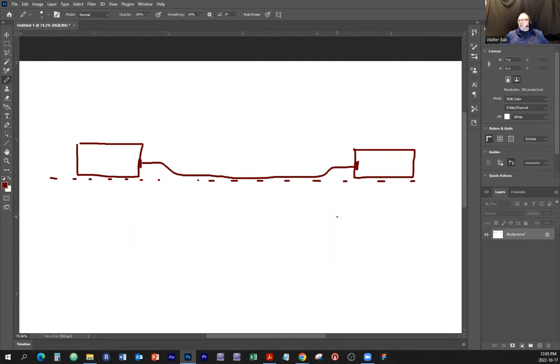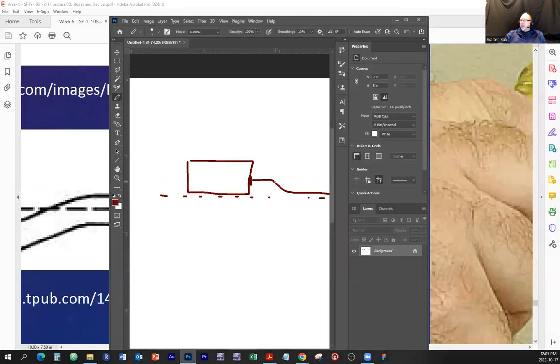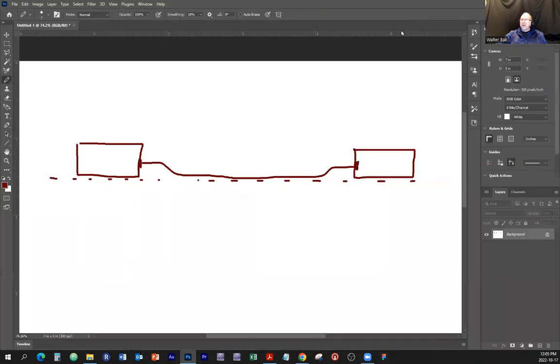And if you think it's simple, if you're a beginner, well, you know what, we're going to have some fun with that. So that's why we need to have that box offset created. So you could bend the pipe to create a box offset. Never use the alternative where you just have the box and kind of stretch the pipe and put it in. It's going to look like, don't do that, all right?